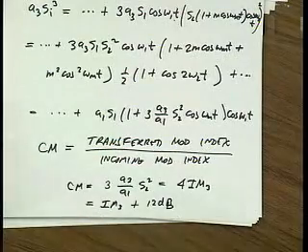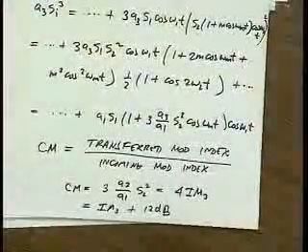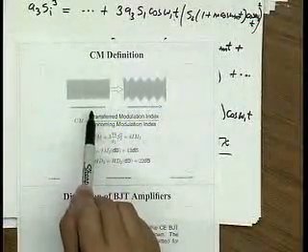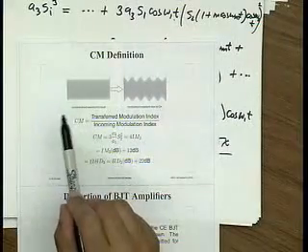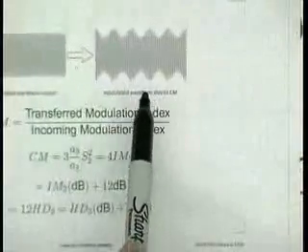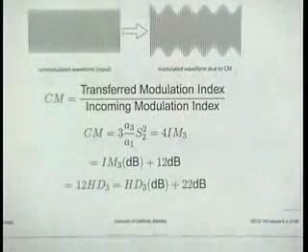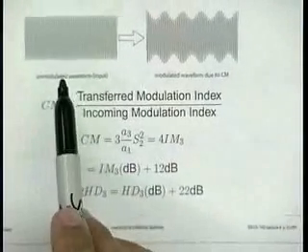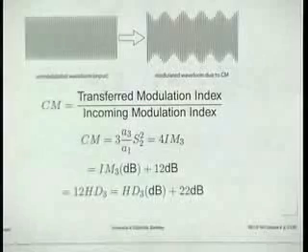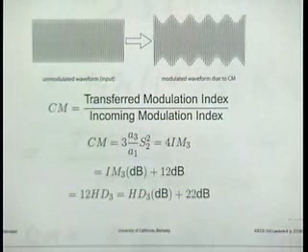Okay. Now this sounds very complicated, but a picture is worth 1,000 words here. So let's look at the picture. This is a simple picture. I have an unmodulated waveform coming in. It goes into a nonlinear system. Some other signal is being modulated, and yet at the output, at frequency omega 1, I see amplitude modulation. So this is why we call it the transfer or the cross modulation, because this signal was not supposed to be modulated. Again, this is the channel showing the soccer, and these wiggles are somebody dancing on the screen. So that's what we don't want to happen. Okay? Any questions about cross modulation?